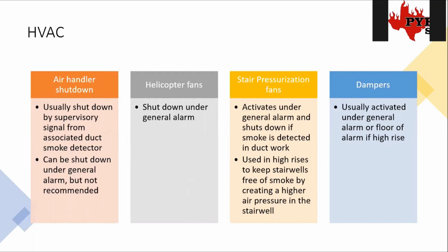It screws up their compressors during like an annual inspection where we're triggering alarm after alarm after alarm and shutting the unit down time after time after time. It's really hard on the units, and it's not required by code. So we try to get them to let us set it up so that only the duct smoke detector on the unit will shut it down.